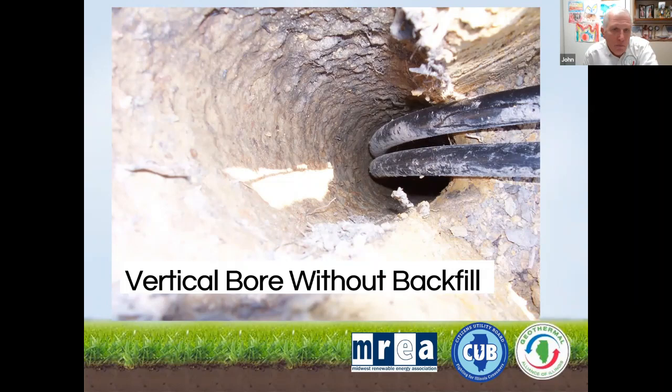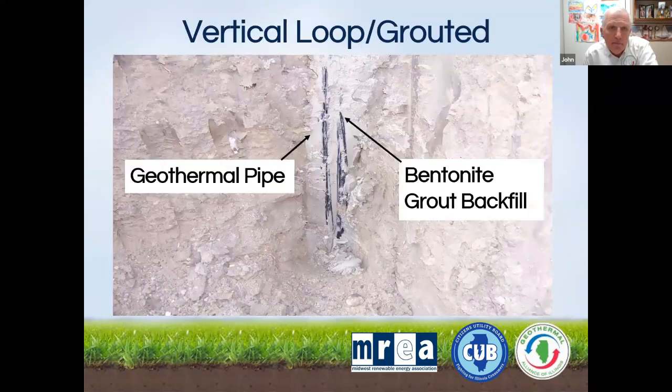And then when that borehole is dug to the prescribed depth, the piping is dropped into the hole, and almost immediately that borehole is grouted with a bentonite grout. And this is important for two reasons. Number one, when we've bored into the earth at those kind of depths, we've exposed the aquifer to potential pollution. So we want to reseal that. And that's really important, number one.